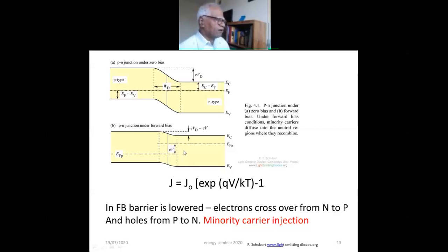So the PN junction is actually a minority carrier device. I want you to please understand this. It's a very important thing, and many times it is not fully appreciated. And this is different from what happened at the metal semiconductor. The electrons went in the metal also. They were electrons, so that was a majority carrier device. Here, when it comes to the P side, the charges that come are electrons, and these electrons are minority carriers. So what you have is minority carrier injection.